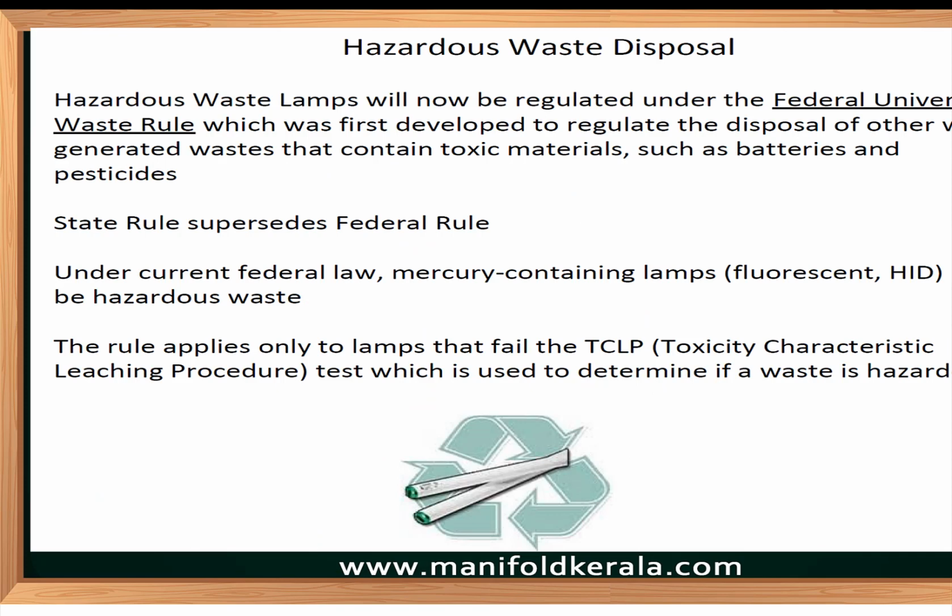So hazardous waste disposal. It's very important that many of the lamps that we have discussed, usually high intensity discharge lamps, contain mercury. Even CFL contains mercury. So mercury is a toxic material and we should limit its quantity. Understand? So nowadays, for disposing of these mercury tube lights, they are asking us to replace all these mercury HPMV lamps with LEDs. Why?